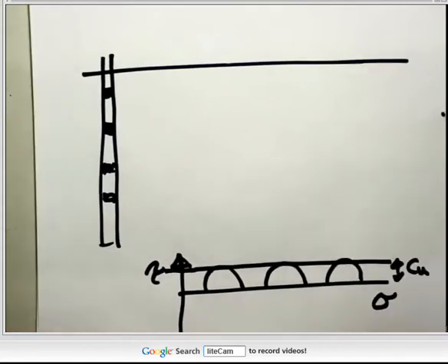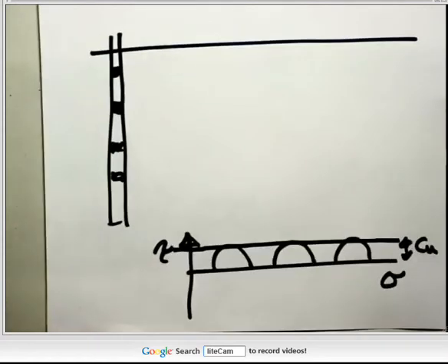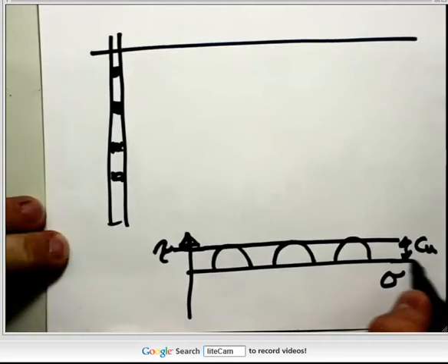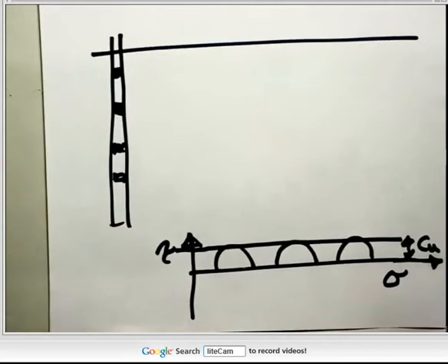In other words, we're assuming for this particular example that Cu doesn't vary with depth. This isn't a necessary assumption. We can perform the analysis when Cu varies with depth. But the mathematics just gets a little bit more complicated, so we're picking this example to illustrate how the bearing capacity analysis is undertaken.